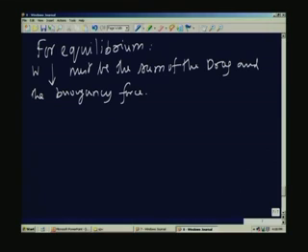And therefore we can just do that. So rho b V b into g, this is the weight of the bob, must be balanced by the buoyancy force rho f V b multiplied by g plus the drag force, which is now given equal to C d.